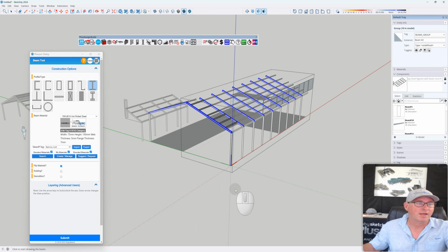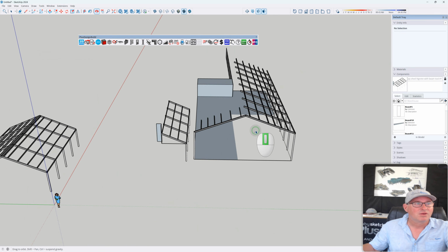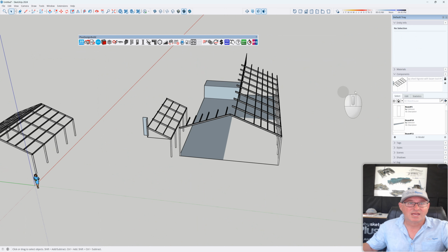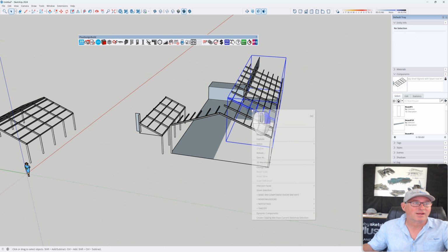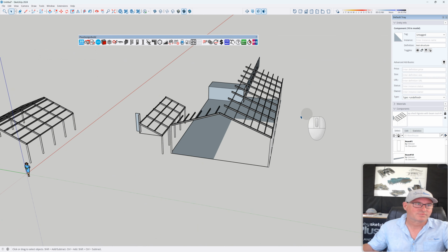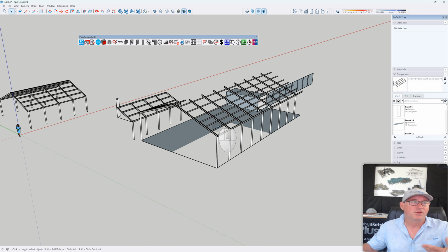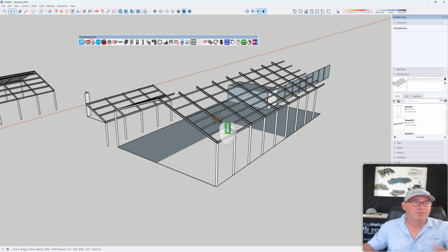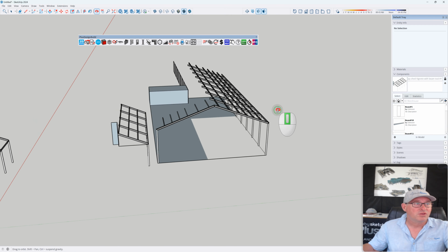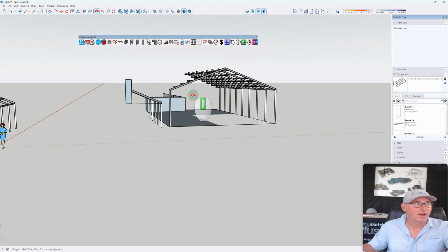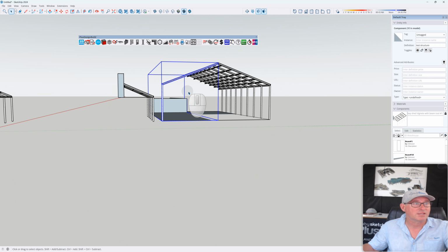very, very quickly on multiple areas. So vignettes: once you've created a vignette that you would normally use as standard, you should save that vignette by clicking on it, right click, save as, and therefore you can create sheds, you can put your wall purlins on, you can put a ceiling in there, you can do a whole heap of things, and essentially you can very quickly create a lot of information in a short amount of time.